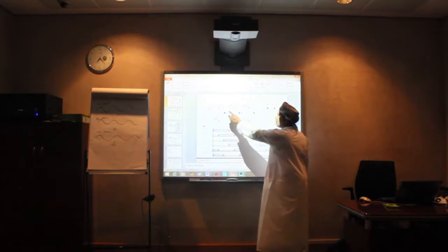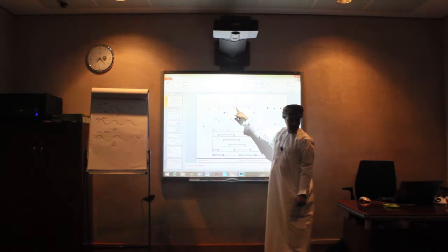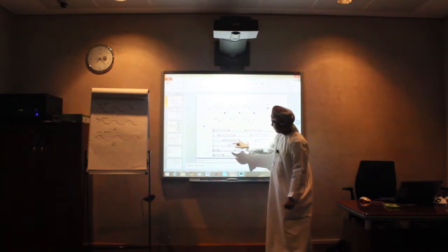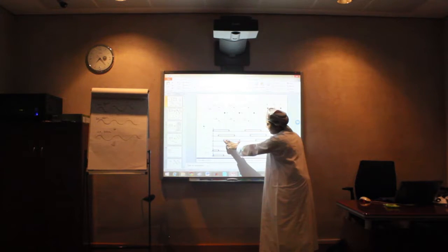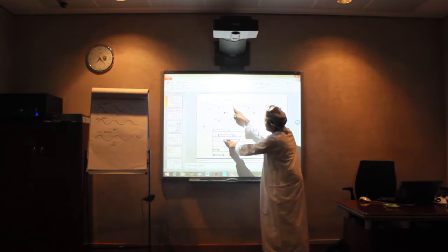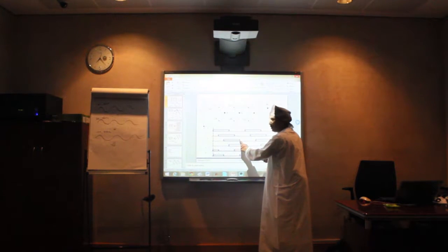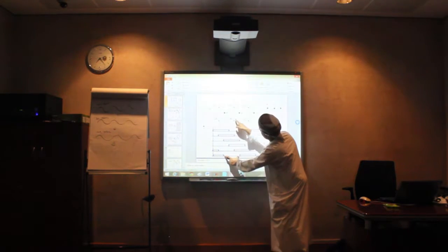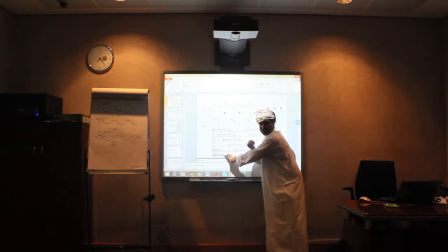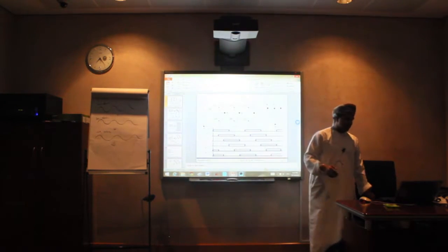And now this switch, the second one, should be shifted by 120, right? So go to switch 3, you will find this is 60 plus 60, 120, right? And it will conduct for 180. And this switch is opposite to that one, so this one will conduct from 120 till 120 plus 180, right? To this point. So you will find that when this switch is off, the other side is on, right? And you can continue for the next 2. Is it clear? So this is how it can be generated.